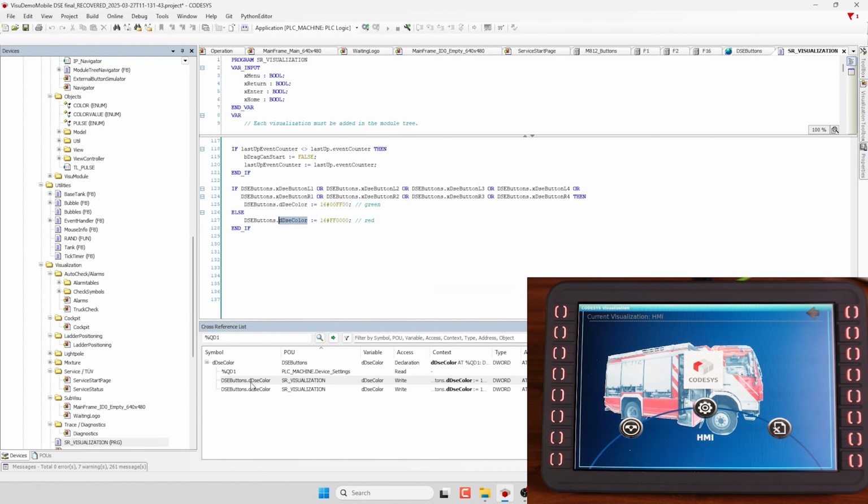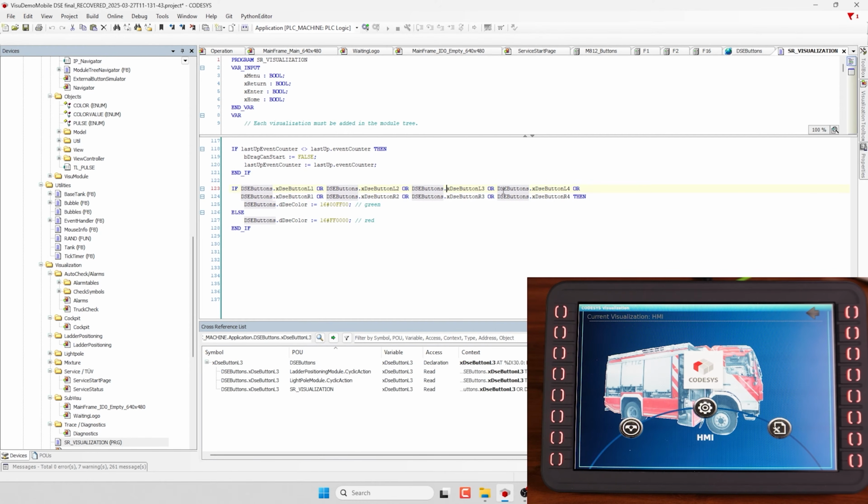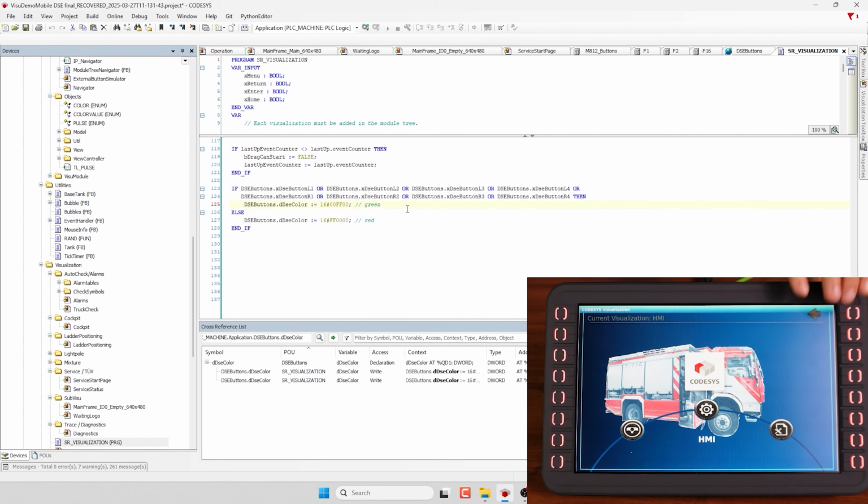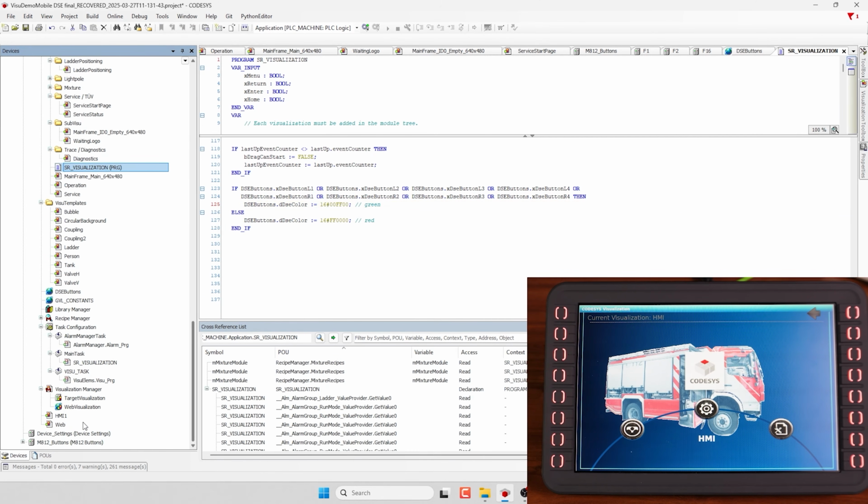If I click on it, I'll be taken here, and look, I have the options green and red, meaning green and red backlighting when the button is pressed. And depending on which button is pressed, that's the color shown here. We can even preview the backlighting here. It really works as it should. So you see, I can refer to these addresses and use these buttons in the program.